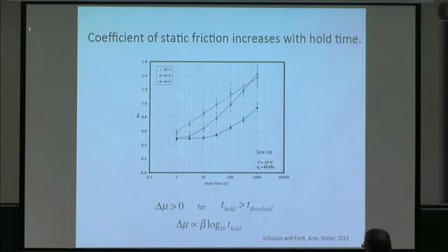If we look at the lowest speed, 10 to the minus 6 per second, then one sees there's a period of initiation where there is no evidence of any static strengthening. The load to resume sliding was about the kinetic coefficient load, if you wish. Nothing happened until there was a threshold period beyond which you start to detect an effect. And at the higher speeds, that threshold time shortens to the point that at 10 to the minus 4 you don't see it at all. It's probably shorter than the measurement time here.